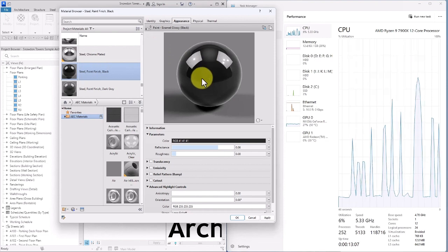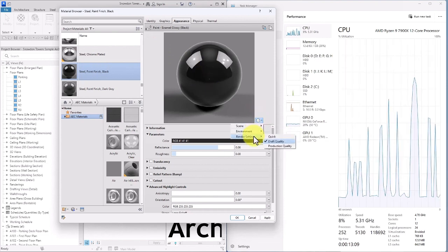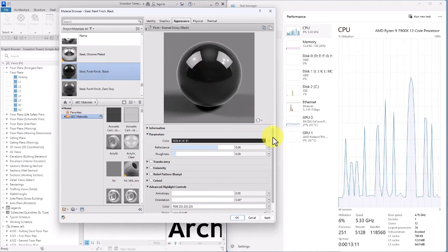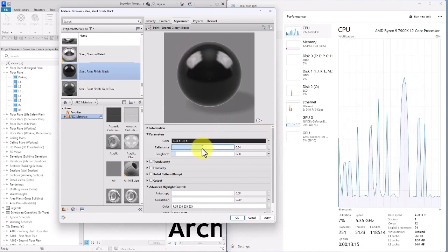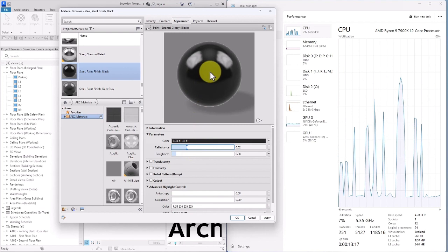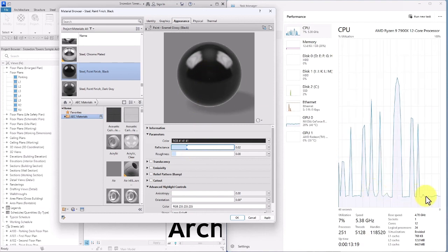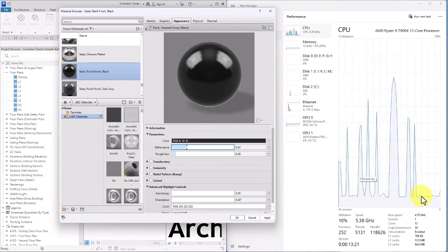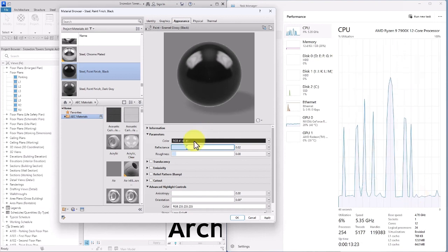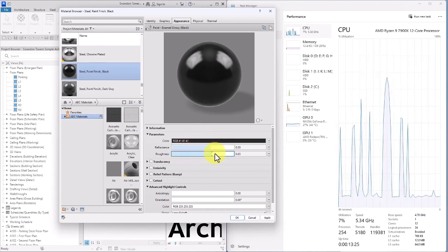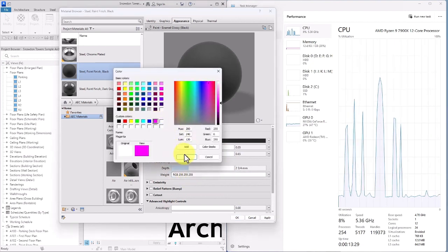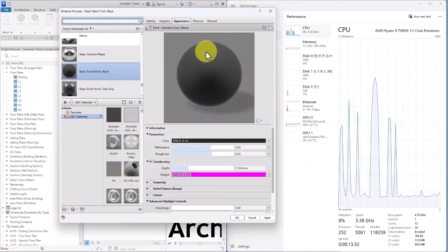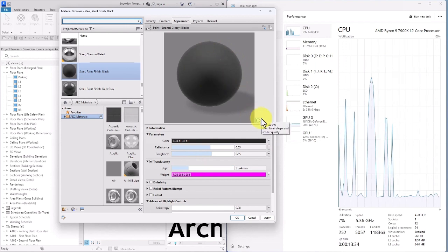However, in Revit 2025, we have this item here called Quick. And as I said before, when we use Quick, not only do we get an instant preview on everything, but also there's no engaging the CPU. So you can go through with your modifications, and at the end, if you wanted to check everything in more quality, you can change this to drafting.